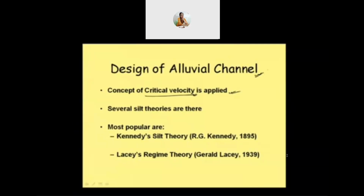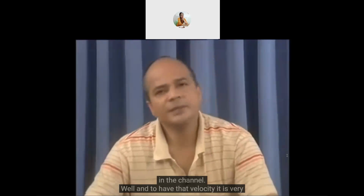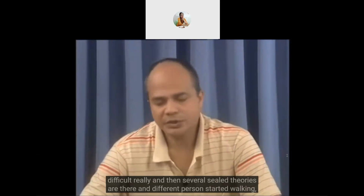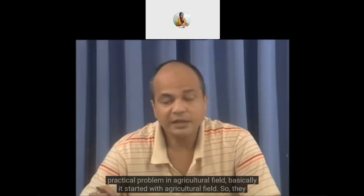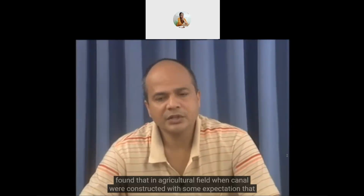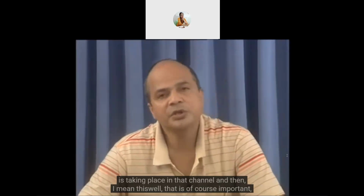Well, this critical velocity is that velocity which will neither cause erosion nor cause deposition in the channel. And to have that velocity is very difficult really. Then several silt theories are there. Different investigators and engineers started working on this because of their practical problems in the agricultural field. Basically, it started with the agricultural field. They found that when canals were constructed with some expectation that they would carry a certain discharge, later on it was found that deposition was taking place in the channel.